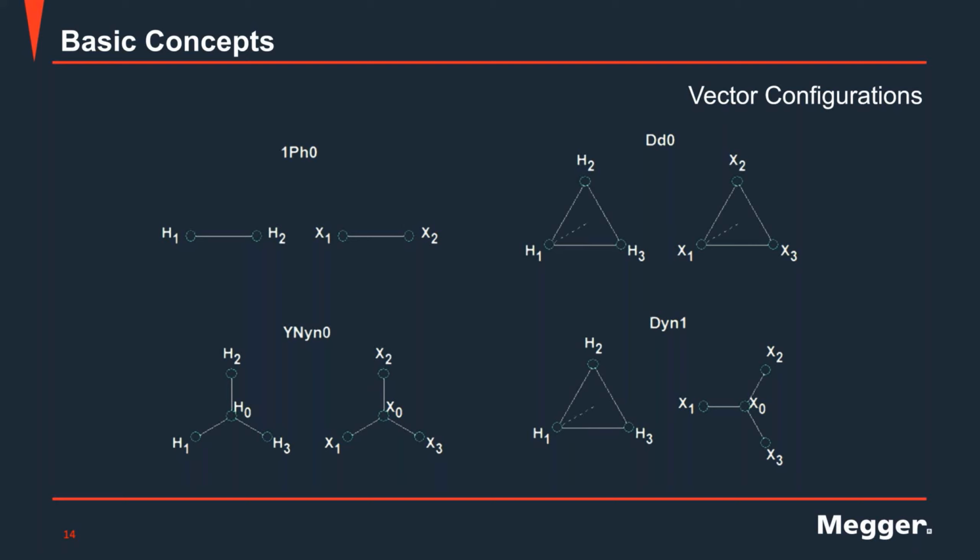So when I perform the test, and as we said before, I have to compare my measurements to my nameplate value to know if my results are within the accepted limits. When I have a three-phase transformer, I need to consider a correction factor. It's not a direct ratio as I showed you before, just dividing my primary by the secondary rated voltages. I need a correction factor, and that correction factor will depend on the configuration of my windings, the connection I have for the windings I'm testing.